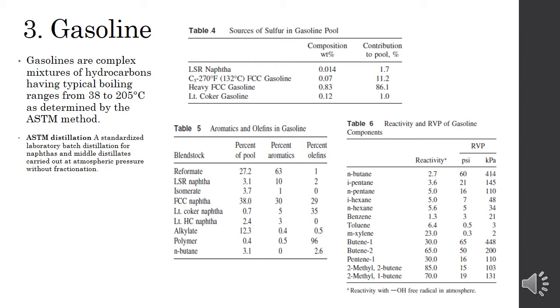Some aromatics have high rates of reaction with ozone to form visual pollutants in the air, and some are claimed to be potentially carcinogenic by the EPA, Environmental Protection Agency. Restrictions on aromatic contents of motor fuels will have increasing impacts on refinery processing as more severe restrictions are applied. This will restrict the severity of catalytic reforming and will require refiners to use other ways to increase octane numbers of the gasoline pool by incorporating more oxygenates in the blend.